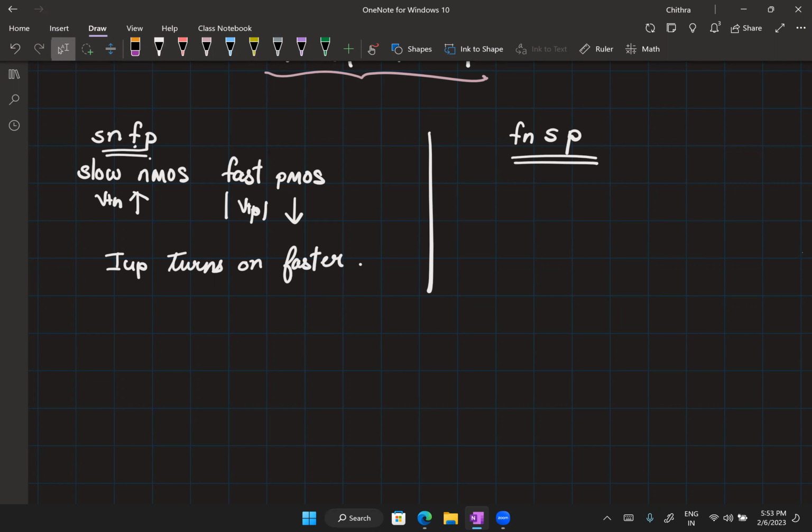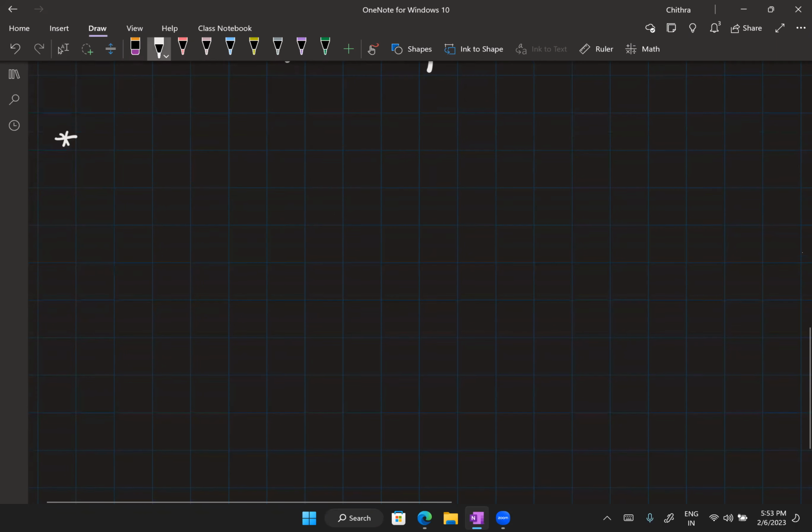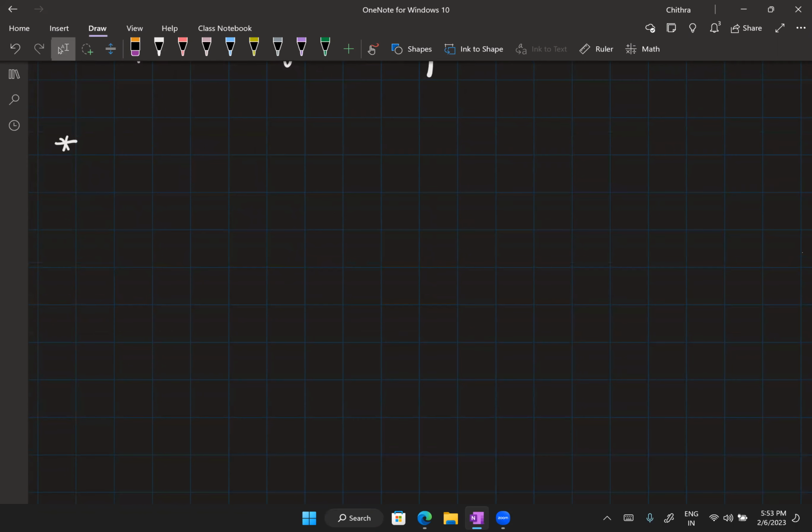So the charge pump is going to push charges onto a capacitor. So even under steady state, our capacitor voltage, instead of becoming a steady voltage, will have some ripple. That ripple is periodic from one period to the next, which is why we call it steady state. I kept saying that it is not desirable, but let us see why. What do you think will happen if I have a ripple on the capacitor voltage? How does it affect our output?